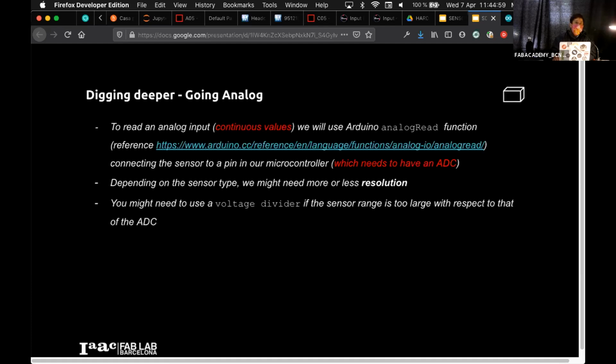So the microcontroller architecture could be 8 bits, and you could represent a 64 bit number with 8 bit numbers, right? So at the end, even if your microcontroller can only have 8 bits as a maximum number, you can group them, and the resolution of the ADC will be satisfied by that. Normally, C already takes care of that by defining types, int, long, floats, etc. It takes care of that for you. That's it.